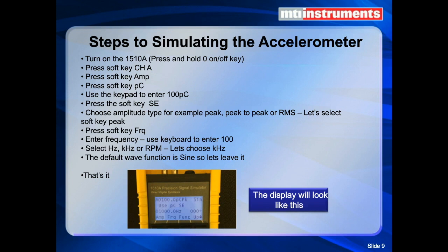So for example, you could go out in the field on the side of a piece of rotating equipment, disconnect your charge amplifier, connect this in place of it, and then check the integrity not only of your wiring, but the charge amplifier and the data acquisition system, so you could rather quickly check the integrity of a whole setup. And you can do it handheld, battery operated. You don't need to drag power cords with you, which can be difficult sometimes in large power plants.